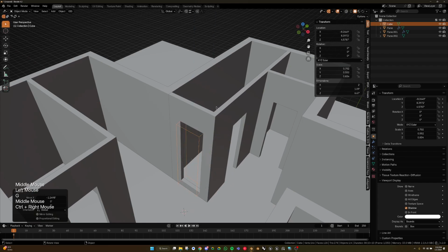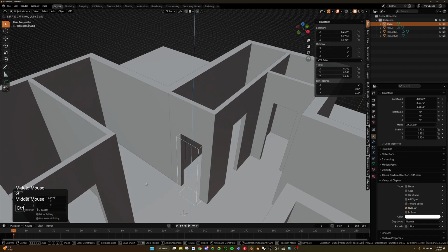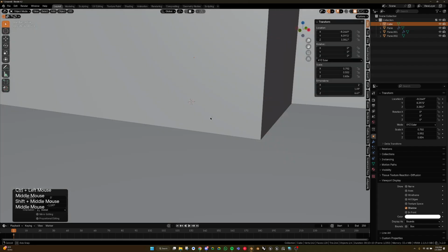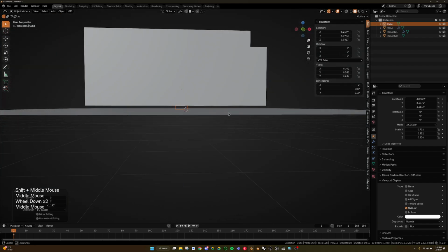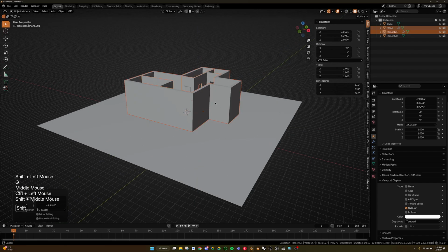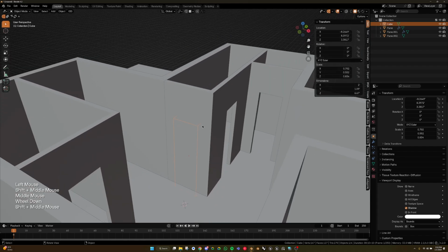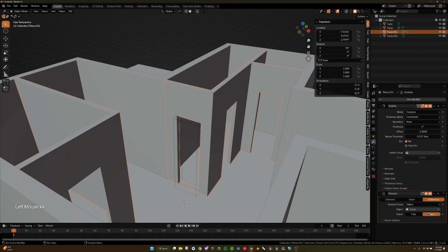Boom. And then I can snap to the face, and it'll go all the way to the base, which looks like the walls are floating. So we can just move that down as well. Now you're gonna see, this is the thing with fast: if there's overlapping exactly at one point, overlapping mesh or faces or edges, you're gonna have to use exact.